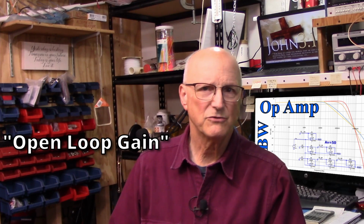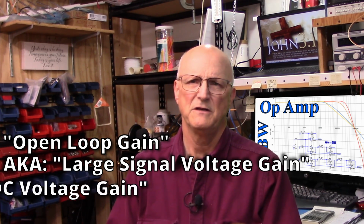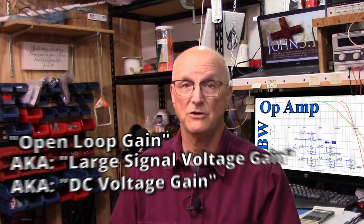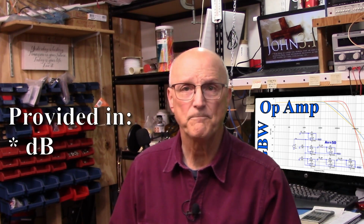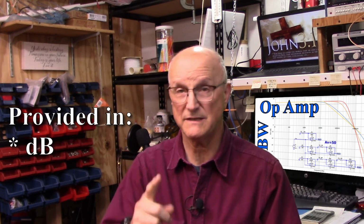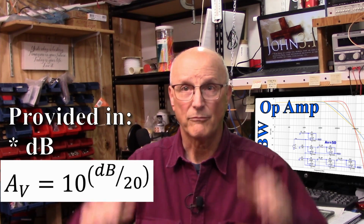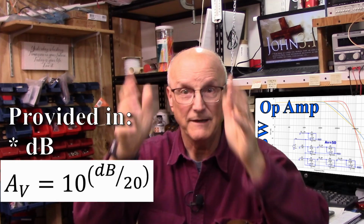It is also known as large signal voltage gain and DC voltage gain, depending upon the data sheet that you look at. In some cases, it's given in dB, and this is easily turned into simple voltage gain with this equation. Voltage gain is equal to 10 brought to the power the dB divided by 20.